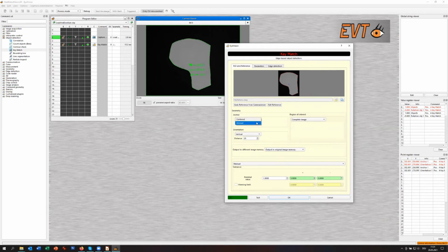And finally, you could also say, I want to have an anchor point. Normally centered is very good, but in this case, the anchor point is this point of the part. This is the point which we return. That means if you have a gripper which fits best for this, you have to change the anchor point to the position which you want to give back to the robot, so that the robot has the right grip point.